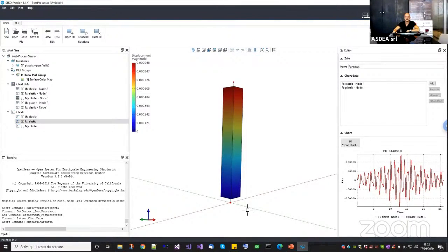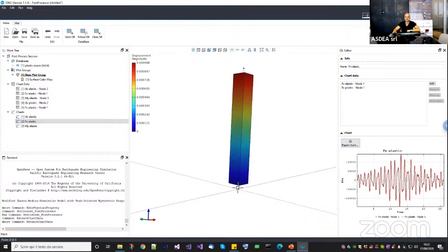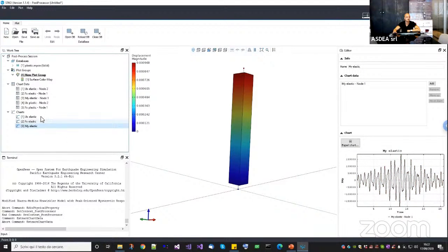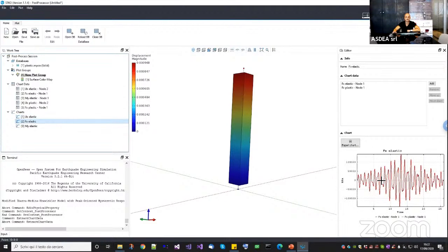Okay, so you do the same with the bending moment, because now you may say, okay, for me this doesn't make sense, because if the plastic displacement is equal to the elastic case, the reaction forces are equal. Since the bending moments are related to the shear forces by equilibrium, I have to have the same values multiplied by 1.3.